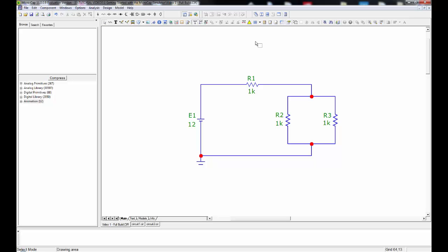One of the very useful tools on this simulator is this thing here. It's called rubber banding. At the moment that looks like it's turned off, so if I was to think of what to change for this component, say I made an error and I want to remove it, because rubber banding is off, I can just lift the component out of the circuit and hit the Del key if you want to, and it disappears, and then replace it with something else. Let me do Control Z, bring it back to the way it was before.